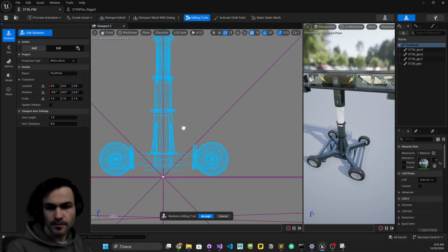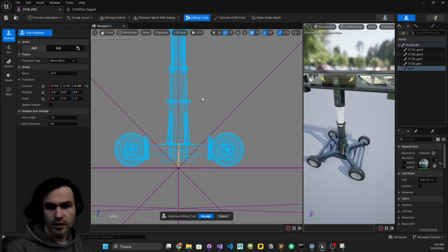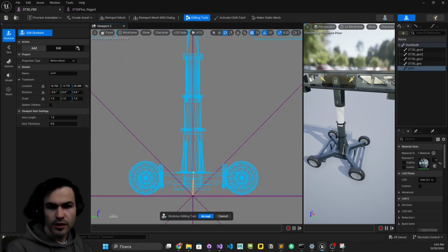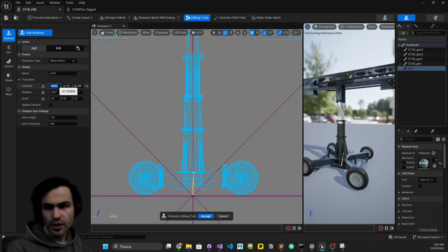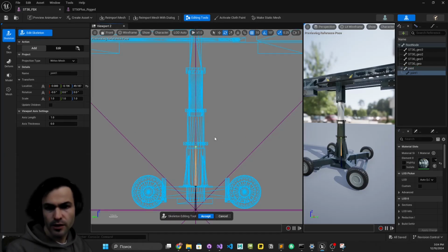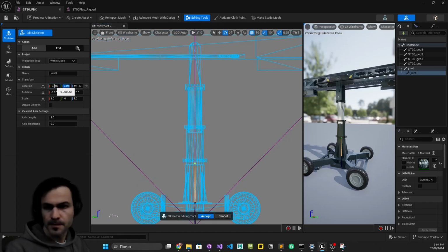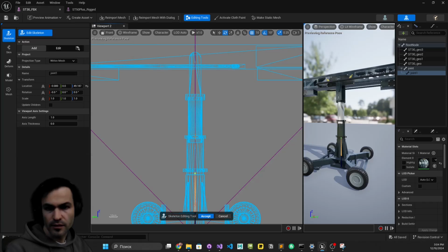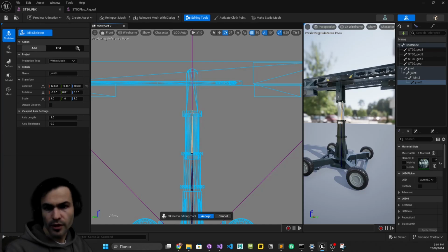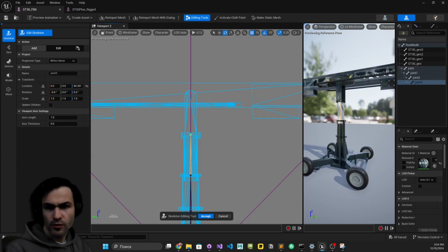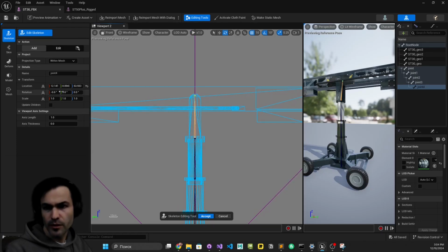So let's start with the root selected. I pressed here, 1, and basically we need to move it only in front, or sorry, in up axis. So we could zero out all the other local axes. Then go to the next one, let it be here. Also zero out all the rest of the axes, then here. And then we go here. And I think that's it. So that will be my column. So that could be even the beam part. Also only in one axis.